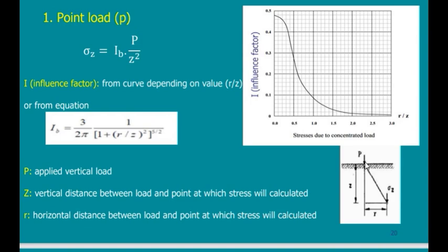Suppose that I have a point load here, point P, and I want to know the effect of the stress of this P at a point that is Z below this point, and R to the side. So in this case, I need to calculate sigma Z due to P, which is the stress due to the load P.